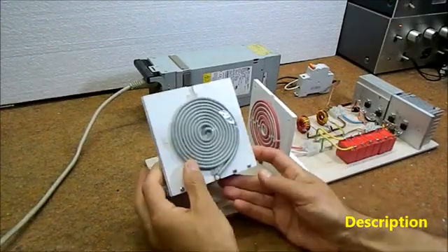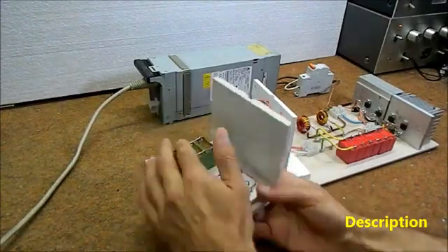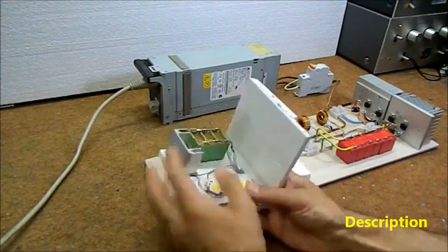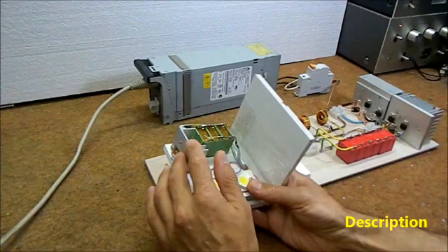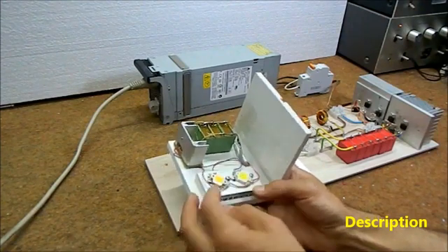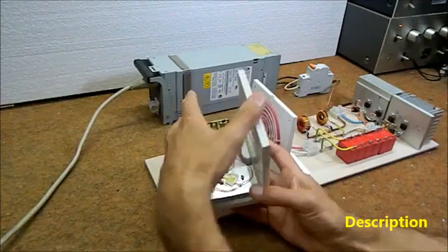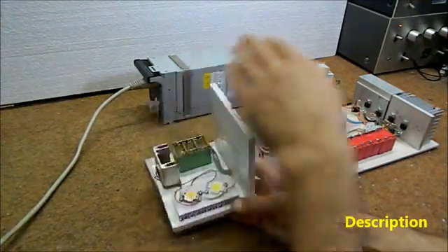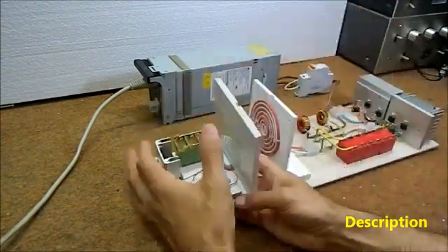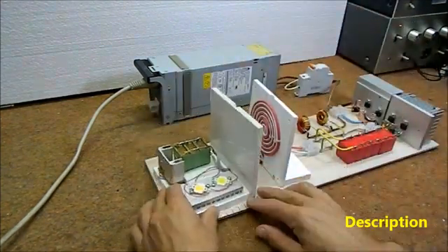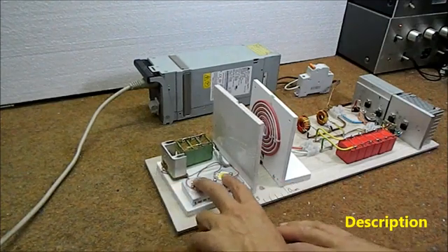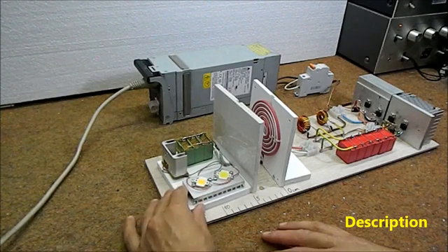This is the receiving coil, and in combination with this capacitor it is a simple resonance circuit. This is a rectifier and voltage stabilizer and is used to drive these LEDs. The frequency of these resonance circuits should be identical to that of the transmitter circuit, for energy transfer losses to be the smallest.